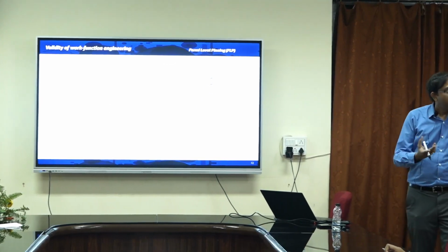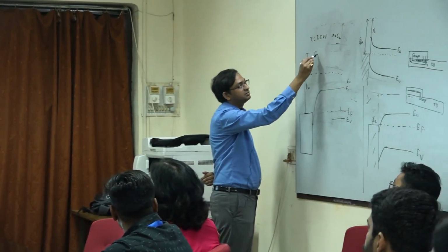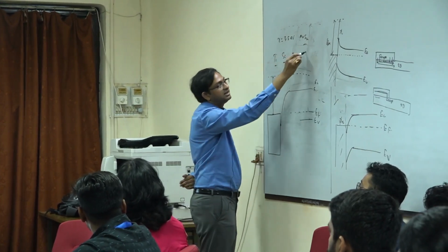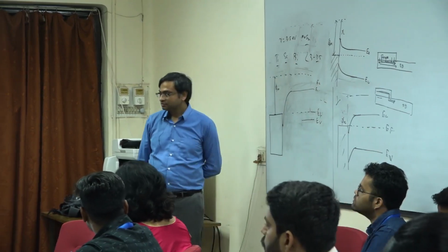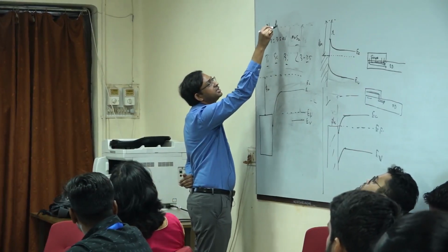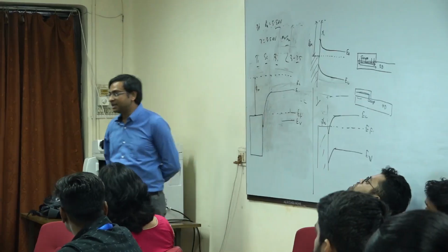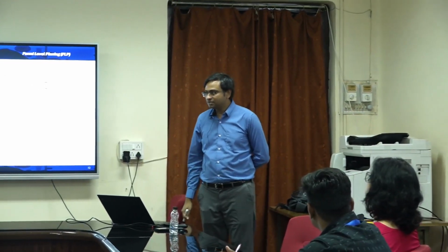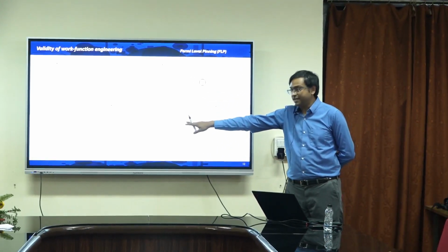That's why we choose metals like titanium, scandium. These all have work function less than 3 or 3.5, right? While palladium, for example, the work function is generally 5.5 eV. Will I choose palladium for making an n-type contact? No. Makes sense?